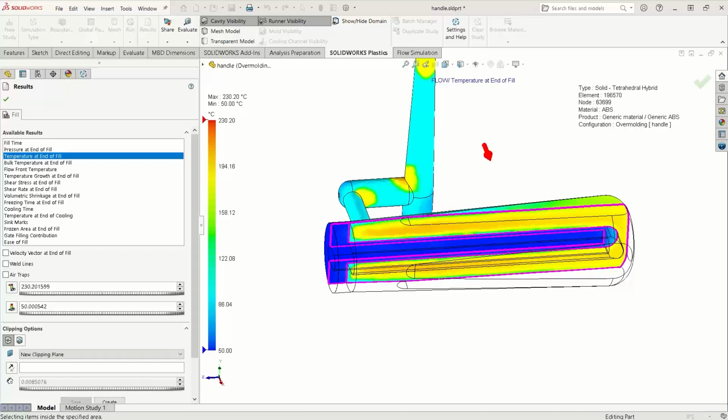So, a 15% glass fiber versus 35% glass fiber. Obviously, the 15% is going to flow a lot more easily compared to 35%. So there's the processability aspect that you have to consider versus the mechanical properties.